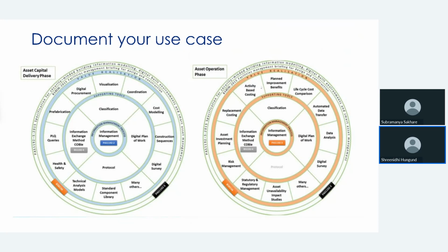If you have not followed a certain naming convention, or a certain mechanism of breaking up the model as per the WBS, then we cannot expect that once you have the model I can do cost modeling, or I can do a prefabricated unit using these models. That is not possible if we don't have a classification system.